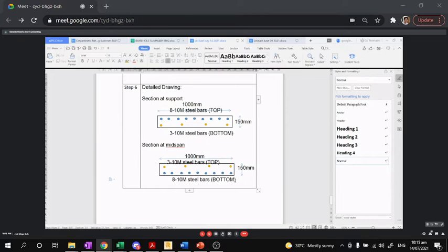And the top portion at midspan is in compression, and what we design is tension reinforcement only. So we do not design the number of top bars, but we will provide a few. We call that compression reinforcement. There is still something lacking. What are we missing? Anybody?